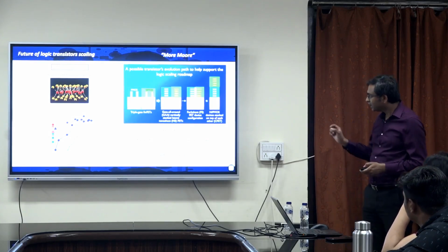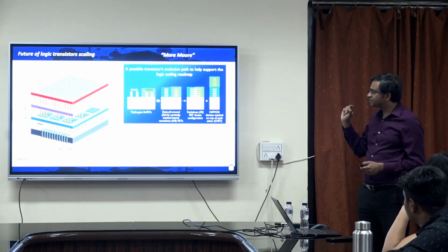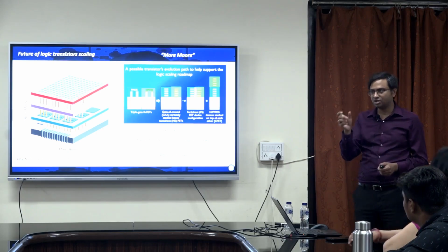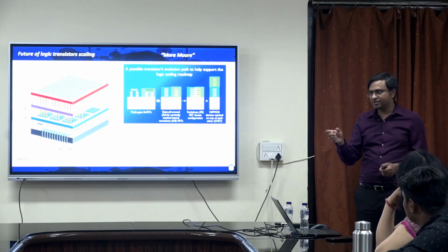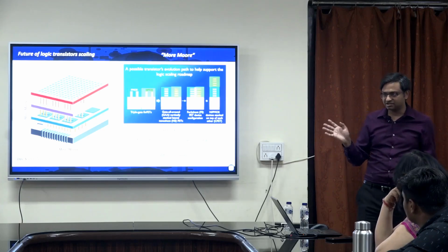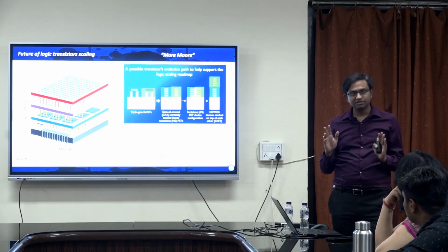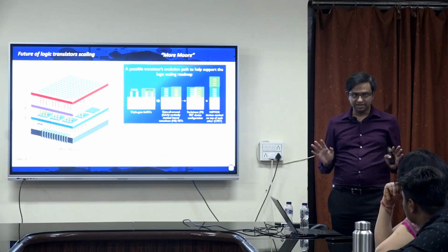Right? Now, if we think about Moore's law, even if we make the transistor very small, today we are talking about the 7 nanometer node. TSMC have already introduced a 5 nanometer node, and there are some angstrom nodes, but I want to first clear the confusion that these nodes have nothing to do with the transistor channel length.